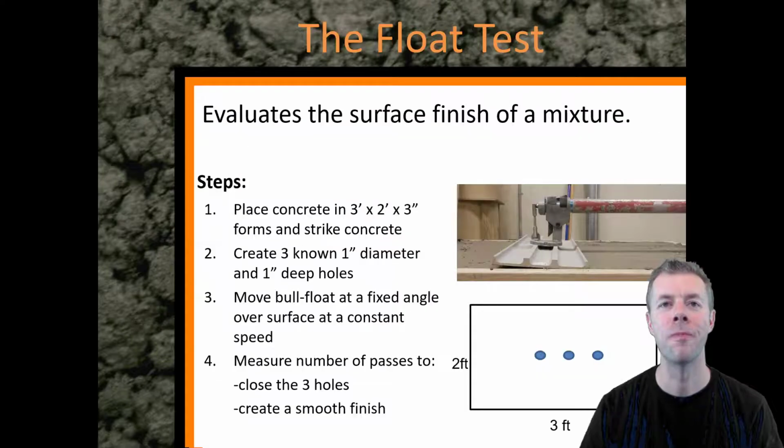It's pretty cool. Let's talk about the float test next. This test is going to evaluate the surface finishability of the concrete. So what we're going to do is place concrete in 3 foot by 2 foot by 3 inch forms, and strike the concrete off with a 2x4.